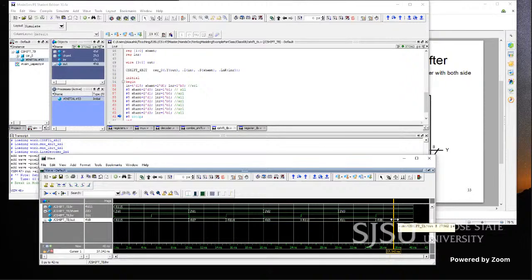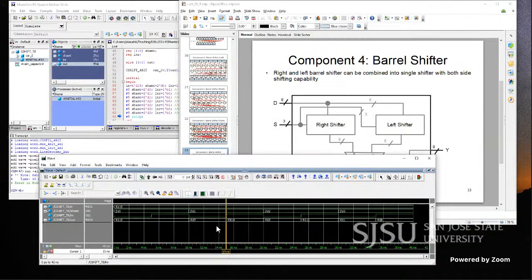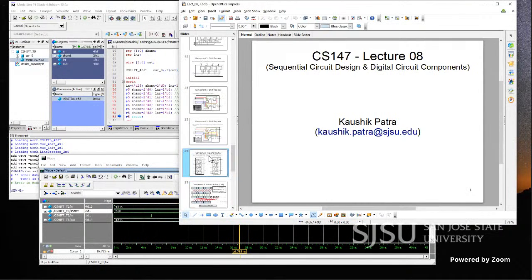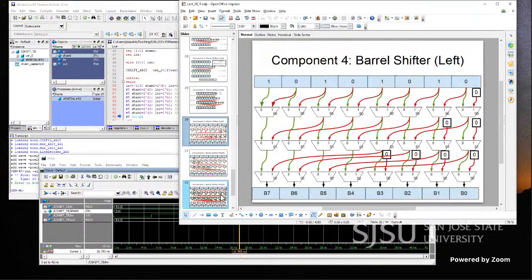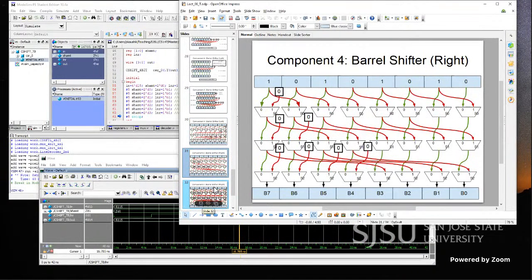So you see, there is no clock dependency in the zero delay model. There is no waiting. As soon as you are querying this circuit, saying compute my shift amount, it just gives you the answer back through that maze of multiplexers. Something like this complex one, the right shifter and left shifter. Imagine how complex it would become for the 32-bit barrel shifter scenario. Question?